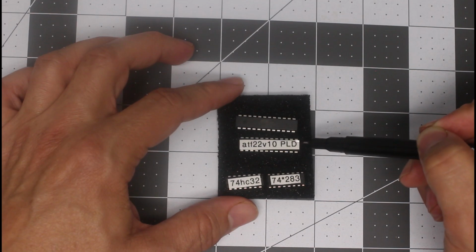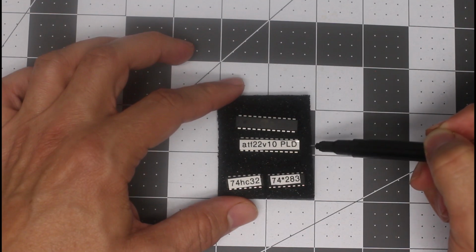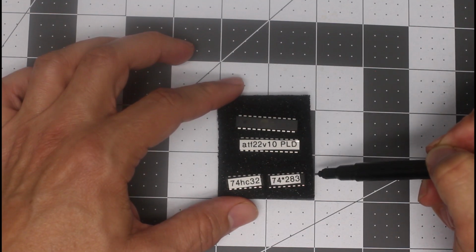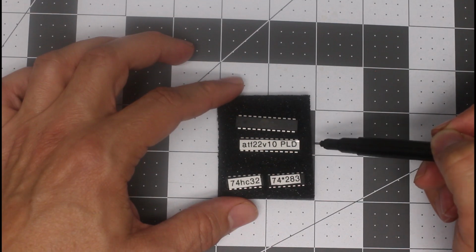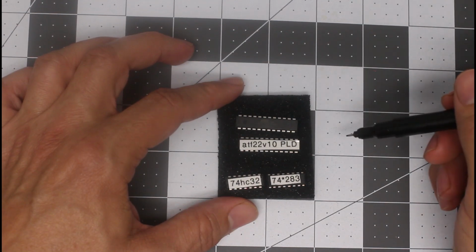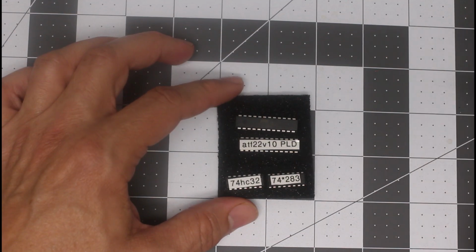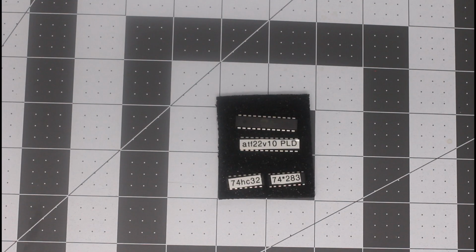So in some cases, a PLD can replace an IC that you don't have in your inventory, and in other cases, it can be used to combine multiple functions and reduce chip count. A PLD is the predecessor to the modern FPGA, or Field Programmable Gate Array. FPGAs are just much more advanced versions of the old PLD. They're configurable like a PLD, but have many more gates and input pins, and are quite a bit faster, and in many cases can replicate an entire CPU.